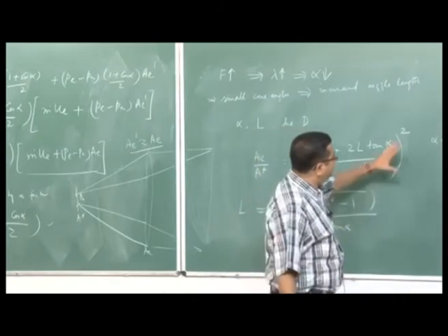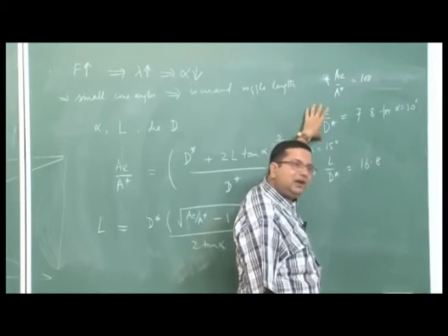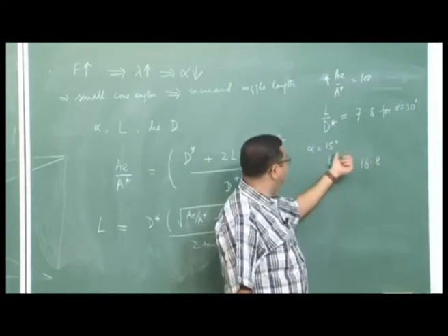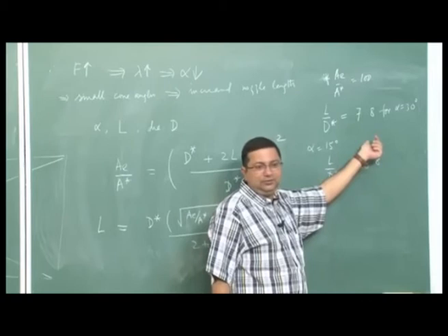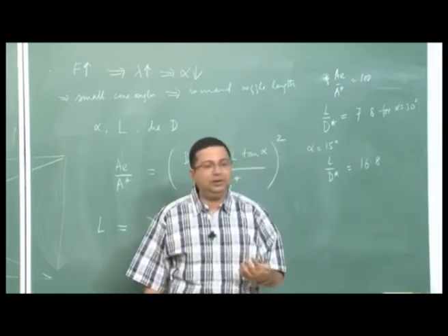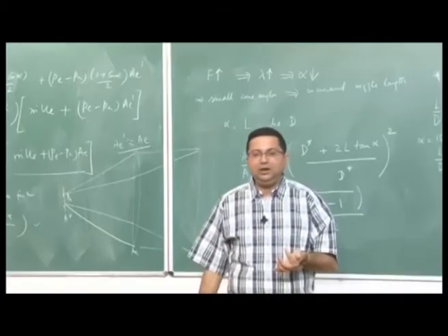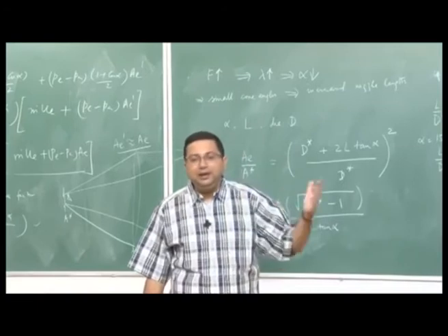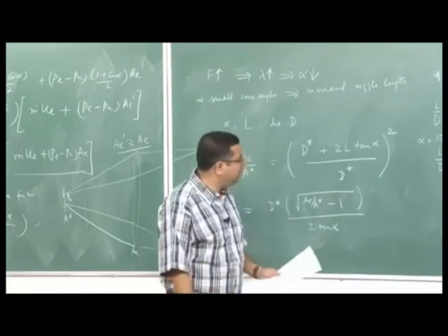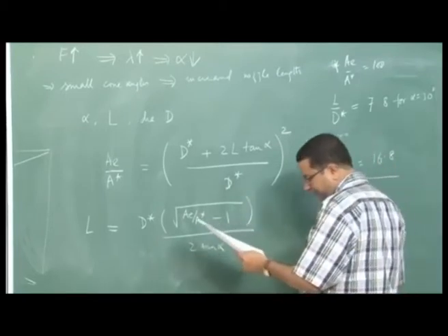So, therefore, if we do not change this length and reduce the half angle, the thrust produced is going to be less, because our exit Mach number has reduced. So, what we are seeing here now is that the exit Mach number, which is dictated by the length of the nozzle as well as the included half angle. So, half angle plays a very important role in the exit Mach number.